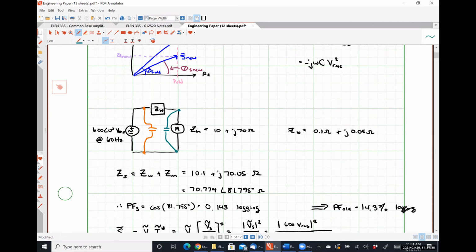But if you're running a large scale industrial plant that has lots of HVAC units and conveyor belts and things like that that rely on induction motors, it's probably going to be cheaper in the long run to correct your power factor where your power comes in at the source of campus, right?